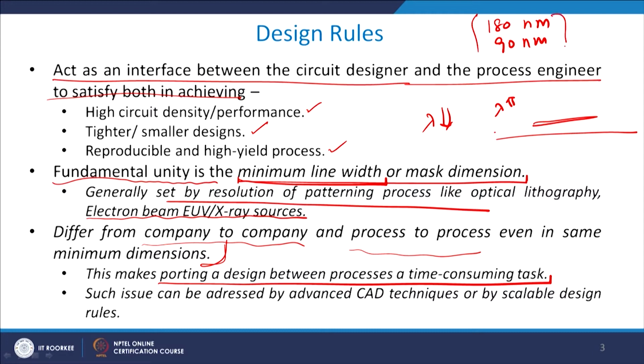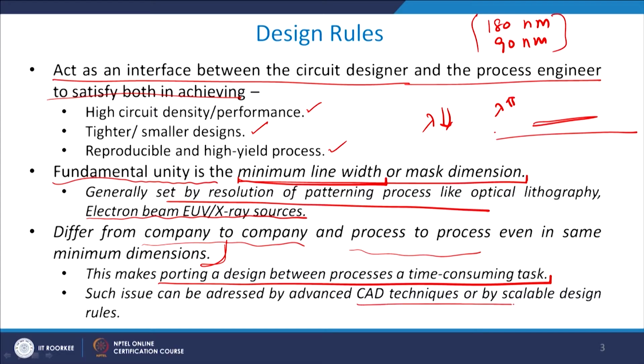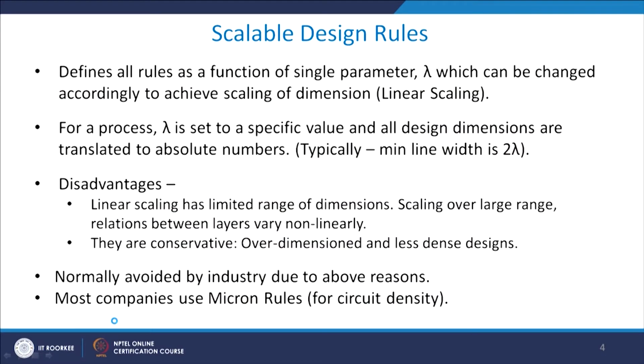This porting is quite difficult, because it is not that you just reduce the dimension by half and everything will go fine. No, it is quite complicated, and it is very difficult to port from either lower to higher or higher to lower. So there are certain CAD tools or CAD techniques which scale the design. So we use scalable design rules. I can either use a CAD tool to do that, or I use a scalable design rule to take care of this. Let me therefore come to what is known as the scalable design rule.